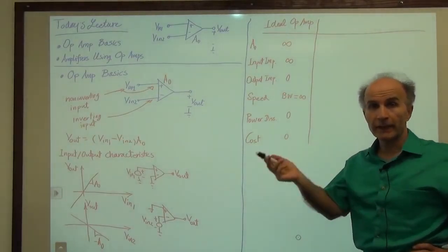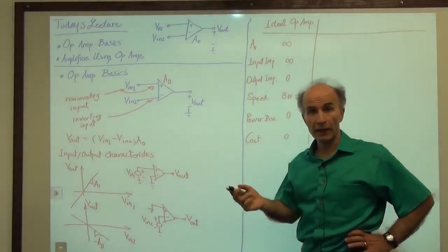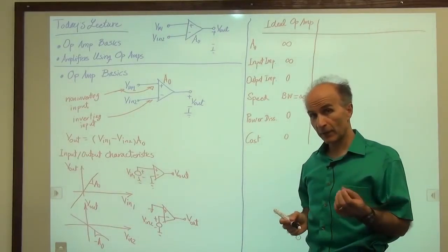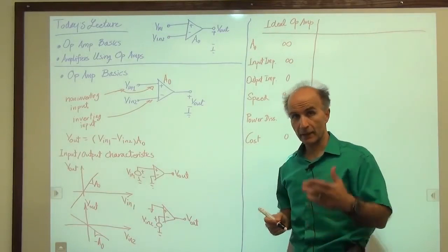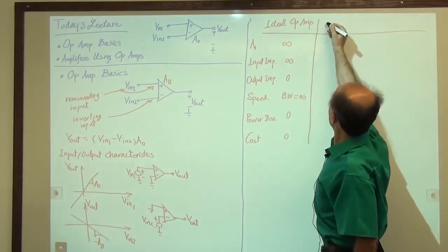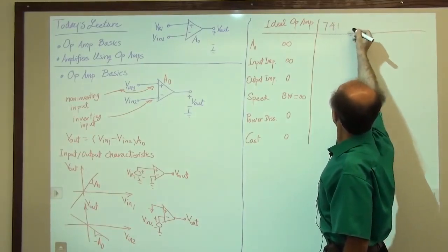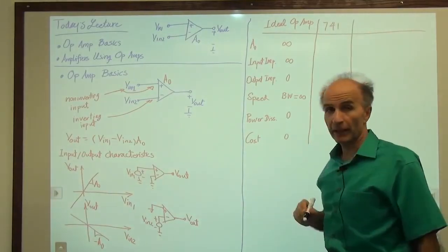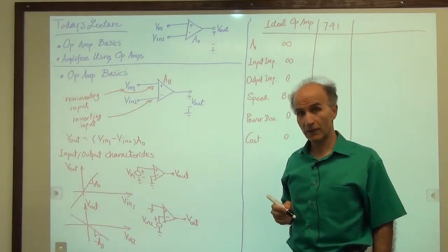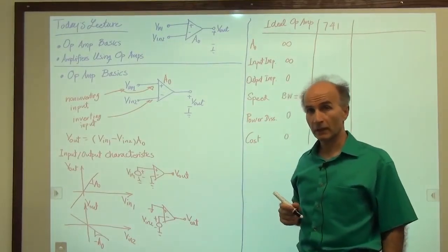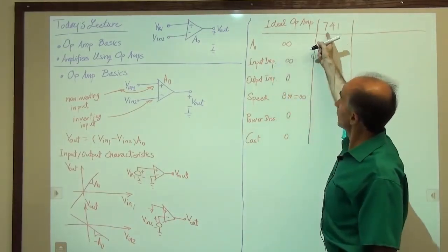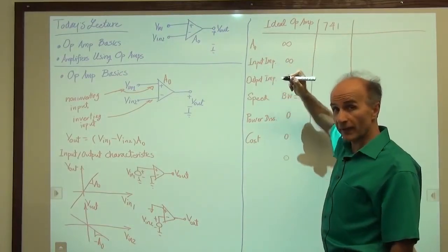Now, let's go and find an op-amp that we can buy, a standalone, off-the-shelf op-amp. For example, the 741. That's a very well-known and easy-to-use op-amp. So 741 is an op-amp that you can buy, and it's been around for, I don't know, 50 years, so it's a very versatile component. Okay, so the gain of this op-amp when you buy it is about 100,000.